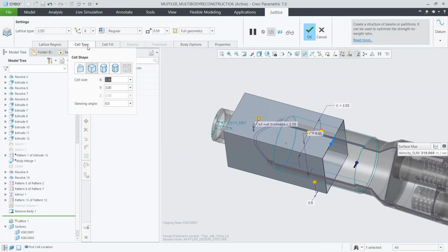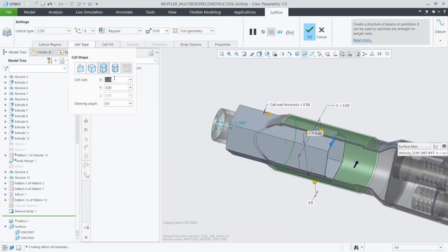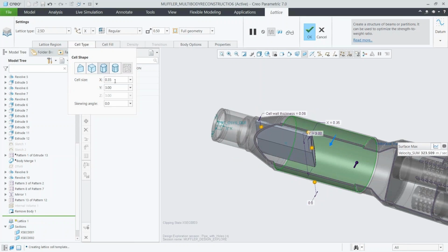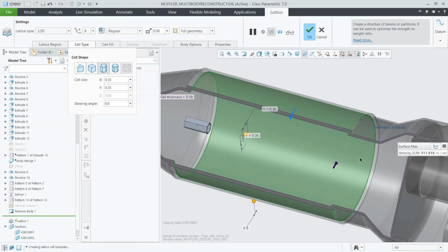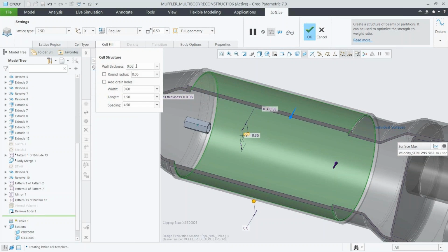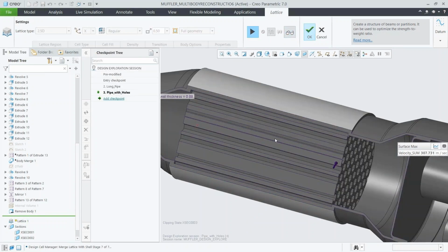And we can do lots of 3D shapes, or kind of like what we're doing here with more of a 2.5D shape in the shape of a hexagon. And we can size that down, scale it, change out some of the parameters. Maybe if we see those wall thicknesses are a little bit thin, we can scale them up more. We can visualize what that would look like, and if we're happy with that change, go ahead and accept it.